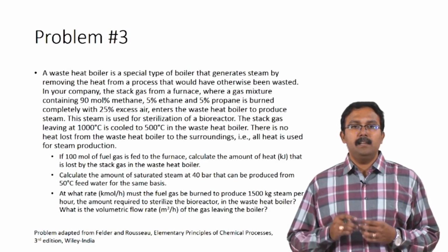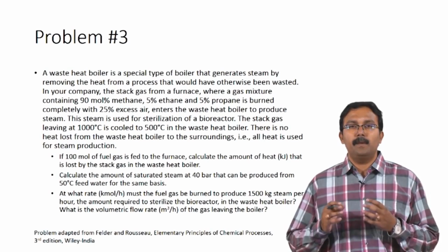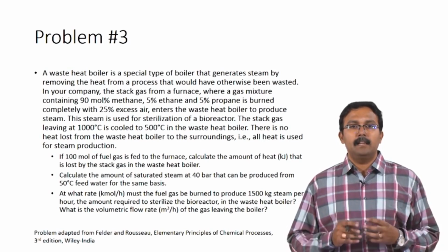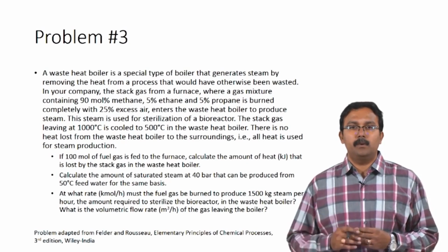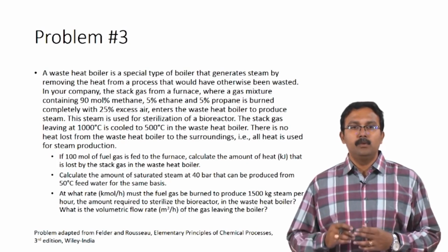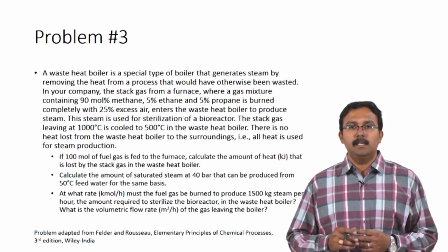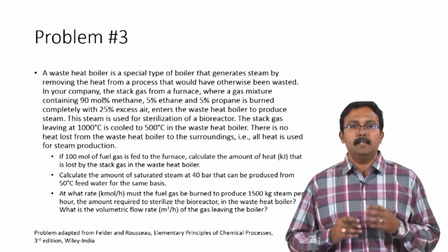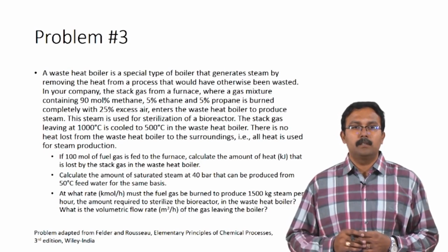The stack gas leaving at 1000 degrees Celsius is cooled to 500 degrees Celsius in the waste heat boiler. There is no heat lost from the waste heat boiler to the surroundings. All heat is used for the steam production only. If 100 moles of fuel gas is fed to the furnace, calculate the amount of heat that is lost by the stack gas in the waste heat boiler.